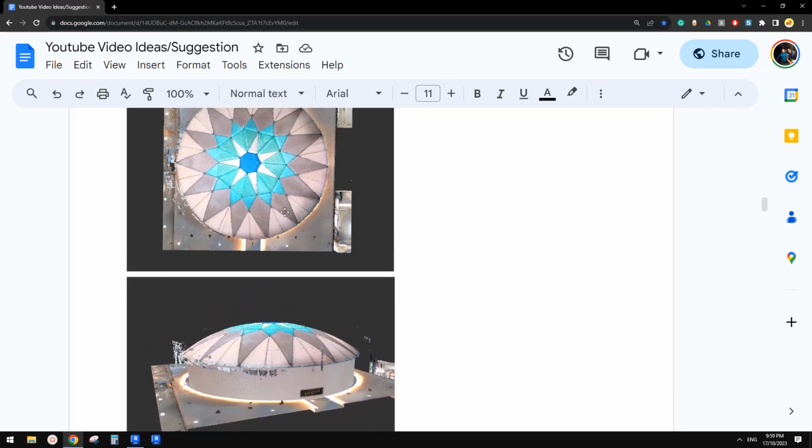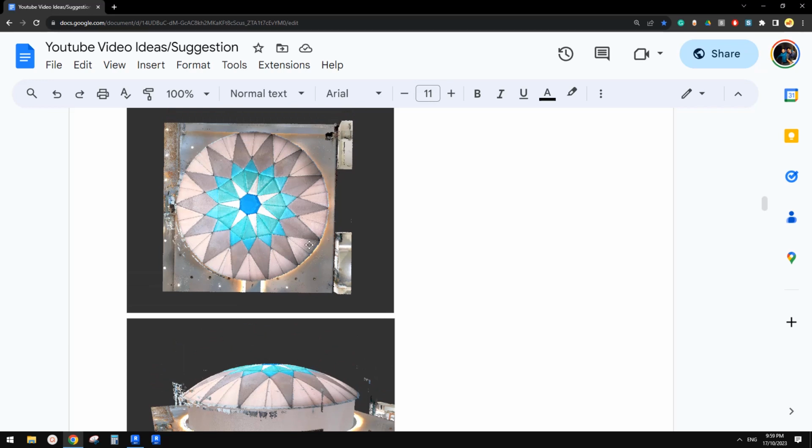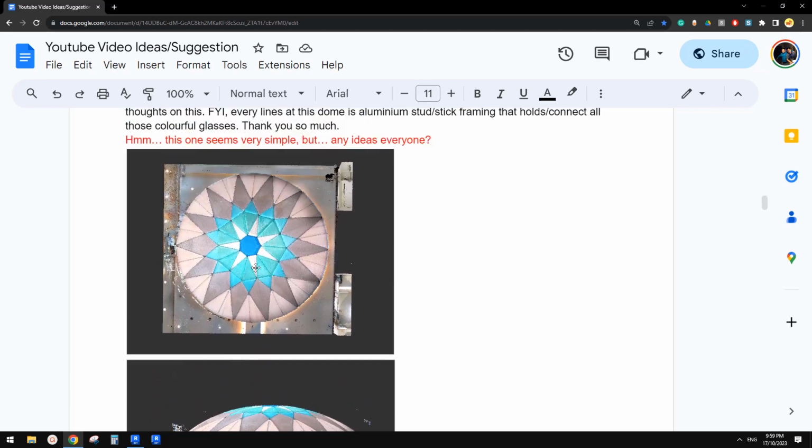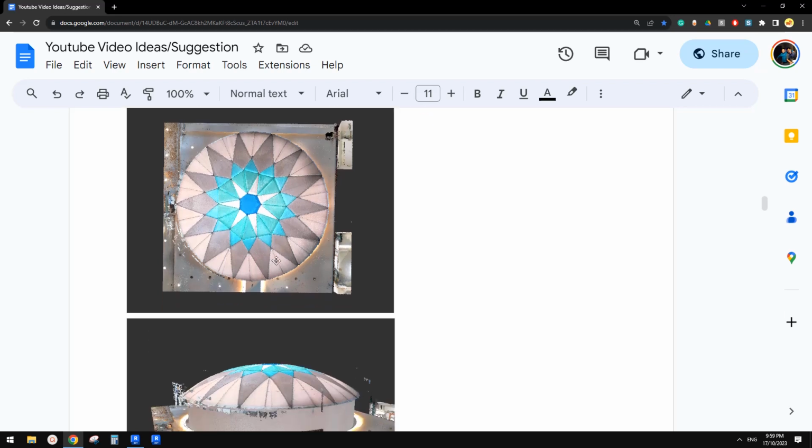When I first look at this one, I think we can probably just create a mask and then try to find a pattern, so we can use a pattern-based family. But then when I look into it, I can't find a pattern that can do this. And then after that I think maybe we'll still use a mask with divide surface, and then we can use an adaptive family to apply them